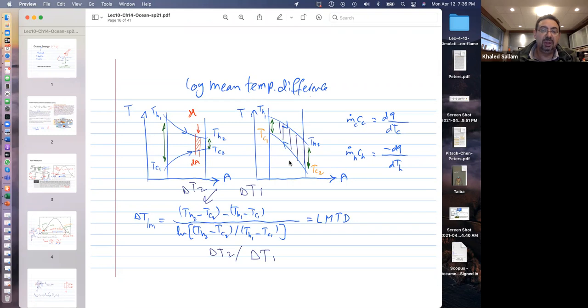If what you care about is bringing very hot fluid to cool it down quickly, or a lot, that's the way to do it. But in parallel configuration, you are pushing them against each other. And so this guy cannot get any colder, this guy cannot get any colder. So you are basically fighting yourself in this parallel configuration, right?